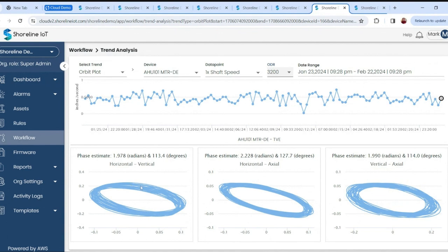actually is. And generally we look at something that's, I think, 60 to 120 degrees is what we call circular. So this one's showing a little bit of an orbit to it, which means that that fan blade probably has a little bit of imbalance to it.